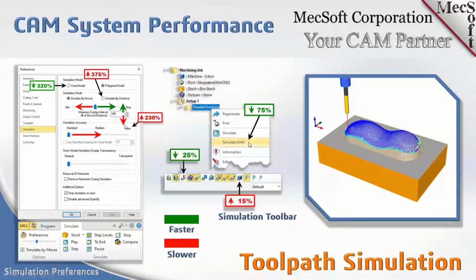Then I also mentioned the trick. If you want to bypass all this and cut to the chase, just right click on your toolpath operation and pick simulate until. That bypasses everything. It doesn't show you anything until the end. It's going to calculate, and then show you the final simulation model. So if you're worried about time, go ahead and use simulate until.